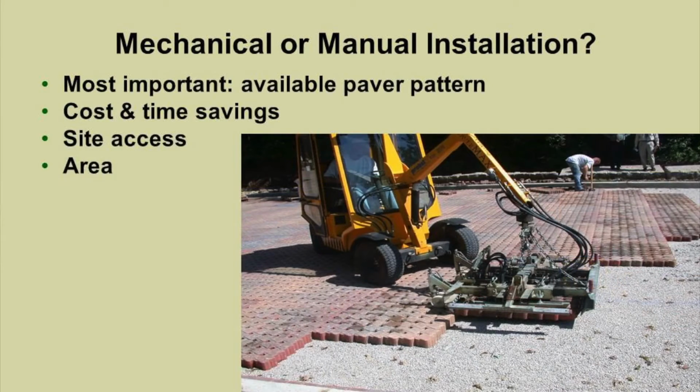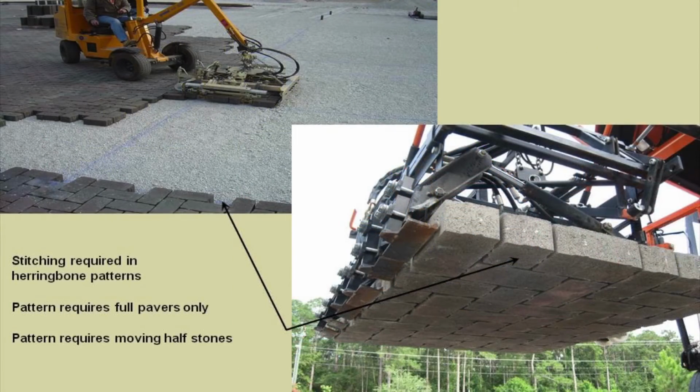Pavers have the unique ability to be installed by hand in smaller applications or in large applications. It's not always the size of the application that matters, but generally larger applications are more affordably done with mechanical installation. It's a very interesting process. It's basically a clamp, specialized equipment we have in the Puget Sound area and all along up the I-5 corridor between here and Portland. I think we have about 6 contractors now that have paver installation machinery, and that really saves time, especially on prevailing wage projects. But you need to make sure there's site access and that available.